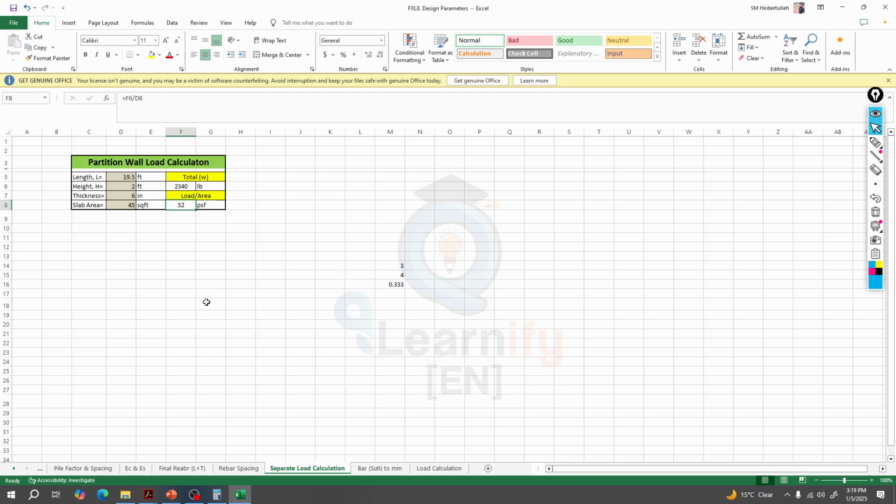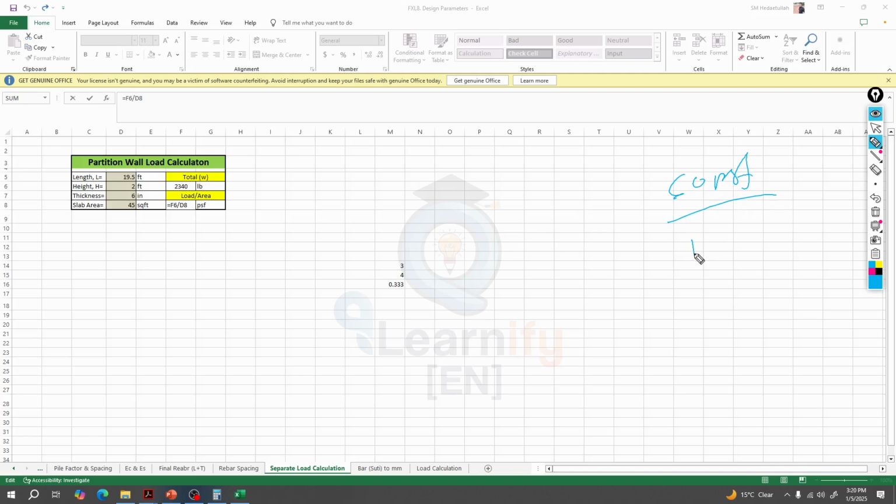And another load like our live load in cantilever or balcony, we have to consider live load. I'll consider live load 60 PSF. You have to provide as per your code. I'll consider self weight will be same, floor finish will be same as previous. Live load will be 60 PSF.